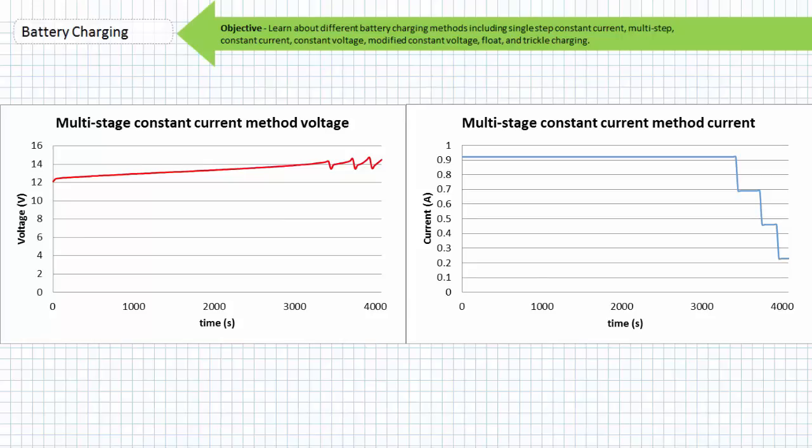Finally, the charger recognizes it has hit the hard limit again and switches over to the fourth and final constant current charge stage, characterized by a 0.1 C20 charge rate. In this case, 0.1 times 2.3 is 0.23 amps, or 230 milliamperes. The charger maintains this reduced charge rate, and the battery voltage again steadily rises to the gassing voltage of 14.4 volts.